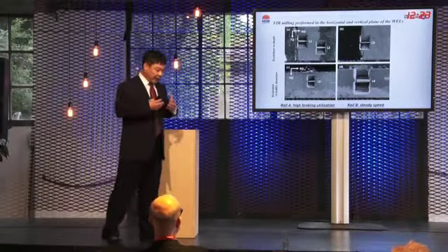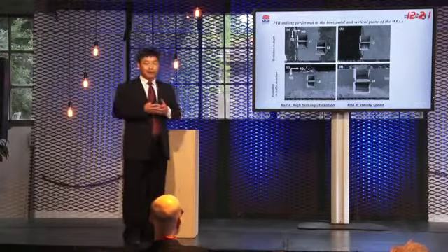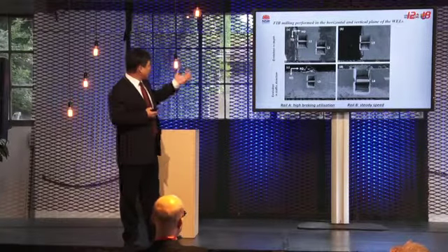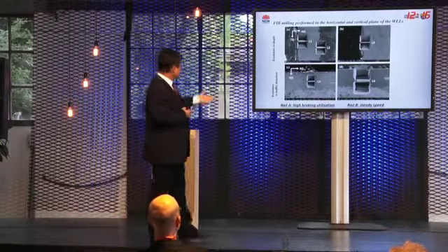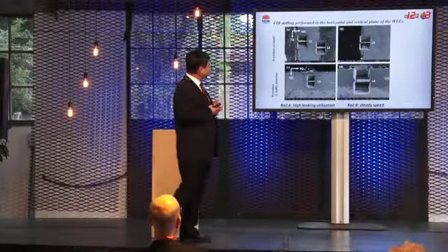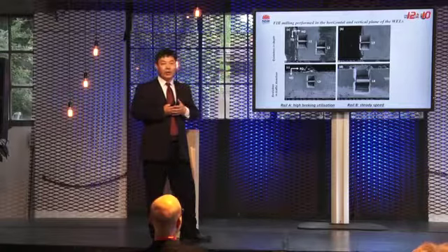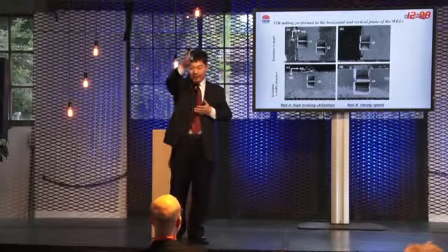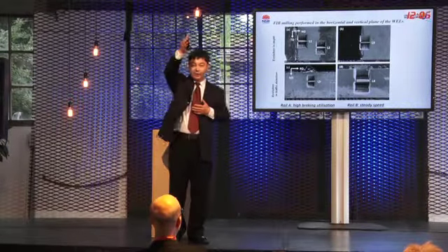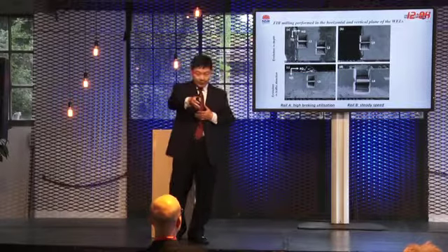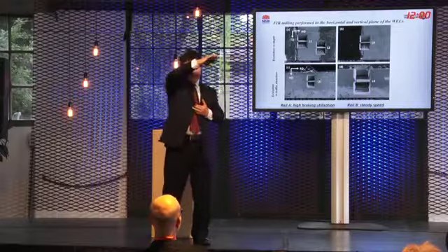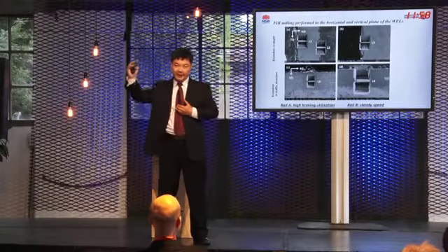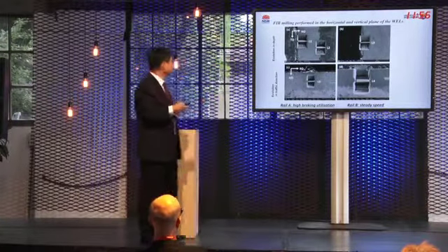Basically, we carry out the analysis by TEM. To prepare the samples, we use the FIB method. You can see here we focus on 2 planes. One plane is in the vertical direction, where we check what changes from the top going in the depth direction. The other is the horizontal plane, where we check what changes along the rolling direction.